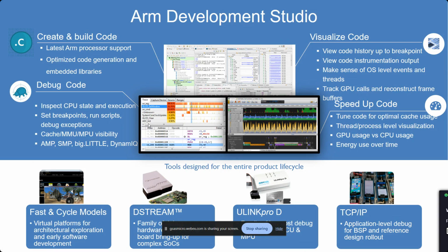Since big little has come up, let me give you an example. If anyone knows it, it will be a repetition for you. As the name suggests, big little is a technology implemented by ARM where the system has multiple processor cores, a combination of a lower end processor core and a higher end processor core. The lower end core is called little and the higher end core is called big. Take an example of a hybrid processor from NXP, earlier Freescale. It's a combination of Cortex M4 and Cortex A5. In this case, Cortex M4 will be little and Cortex A5 will be big.